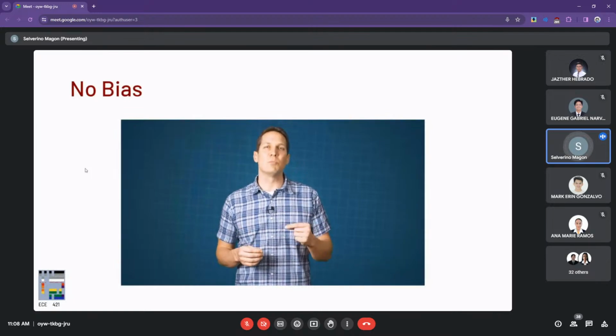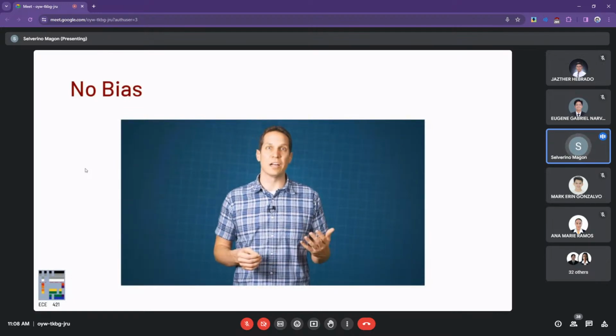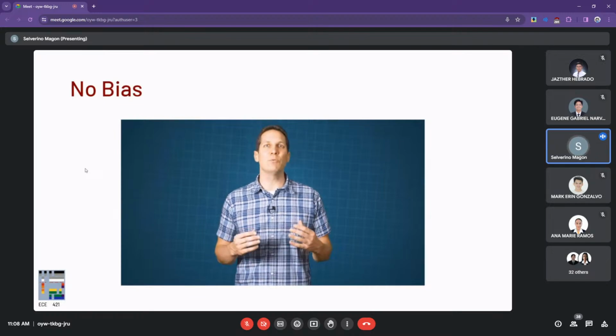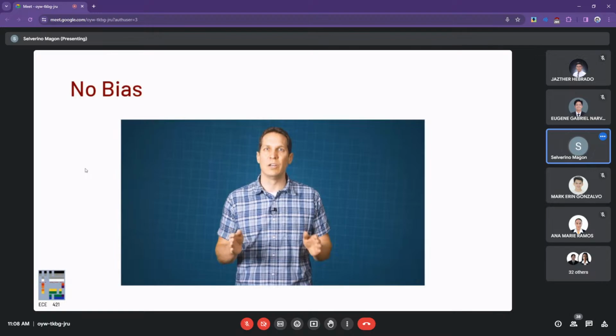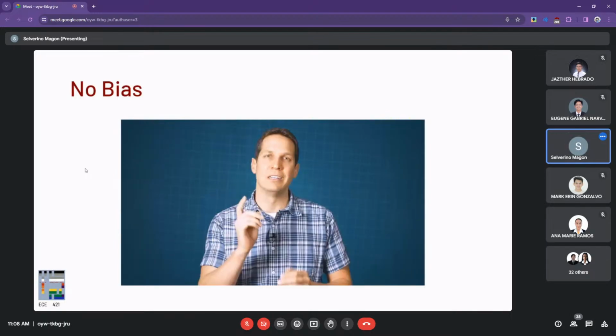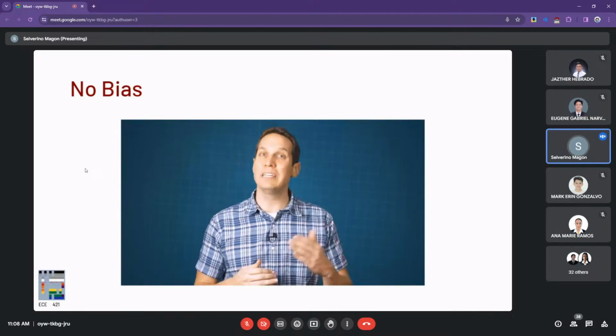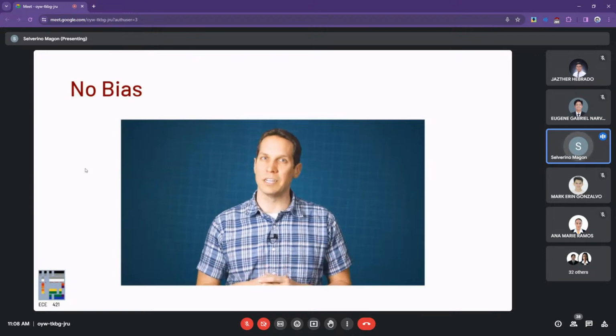Now, if we take a small piece of semiconductor material and dope half of it with a trivalent atom and the other half with a pentavalent atom, that would result in a semiconductor device with P-type and N-type portions, with a PN junction where they meet. In this video, we're going to talk about this PN junction, as it is the basis for diodes.